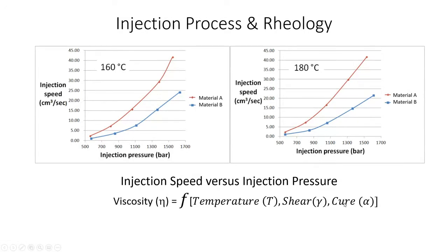And, you know, we are always looking at efficient processes in the fabrication process. So we don't start with a cold mold, inject the material, and then heat up the mold. Everything's hot. And so things are being injected in a hot runner, in some cases in a hot cavity for sure, because we use the temperature to cure the rubber to cross-link it.